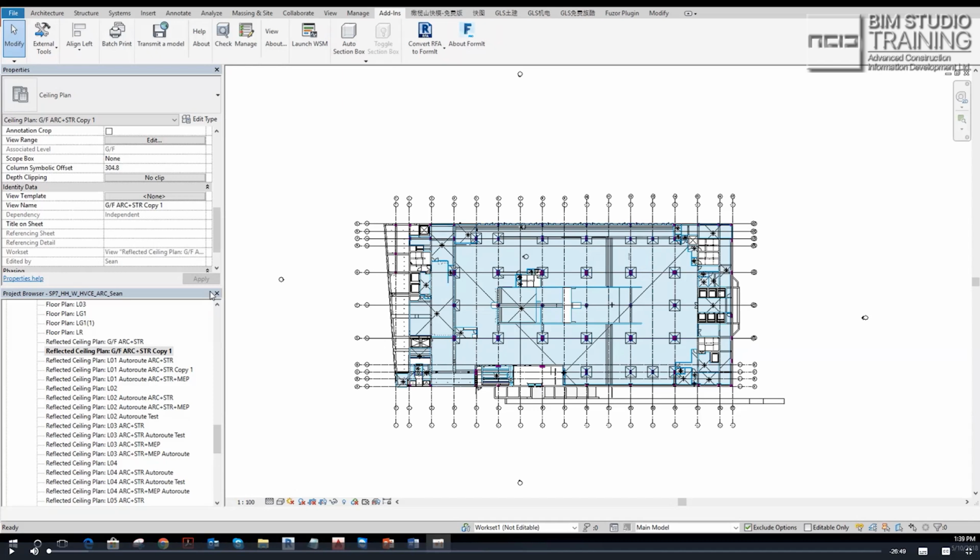Of course, it keeps on changing, all right? But in a simple world, you know the sizes from A to B. So the simple direct answer is run a straight line from A to B, then it's finished. Okay? But reality is not like that. There are a lot of things in between. You cannot run a straight line because of the corridor, the headroom, whatsoever. So to run a duct from A to B, what are the obstacles?